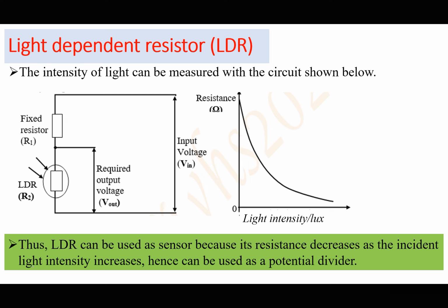What is very important for us to note is that just like the one for the thermistor, we have two resistors in series, although one resistor has its resistance vary with the light intensity, which is the LDR. So we can connect a lamp in parallel across the LDR if you want, or an indicating device here, which can help us to tell that there has been a fall in light intensity or an increase in light intensity, where the lamp can switch on and off.